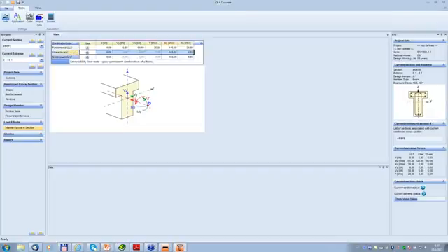You can see that there are two tabs, showing what the combination is like. One is a serviceability limit state combination, and the first one is ultimate limit state. For concrete cross sections or concrete structures, reinforced concrete non-pre-stressed, there are two significant combinations for serviceability limit state and one for ultimate limit state according to Eurocode. Once I defined it, I could also use, for example, the import from our other programs, from Beam or Frame, or I can copy this table from an Excel program.